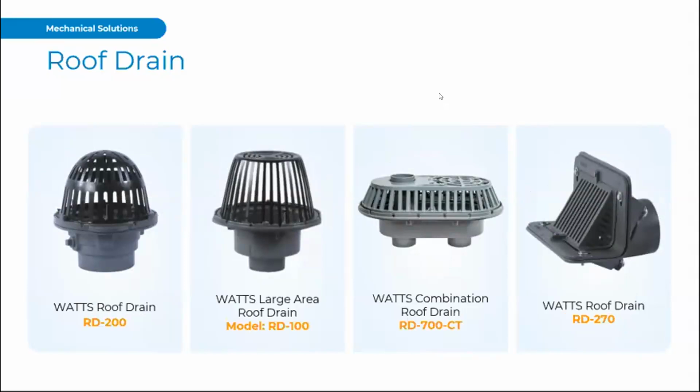Looking at our roofing areas, they again specialize in all the drainage. So you can see some of the newer models that have come out with the combination roof drains, where you've got your overflow and the roof drain standard right there. Your RD100, again, they focus on an interchangeable design. So if you do require the AccuTrol, you're using a flow control roof drain all of a sudden, it'd be the same body with the AccuTrol weir.